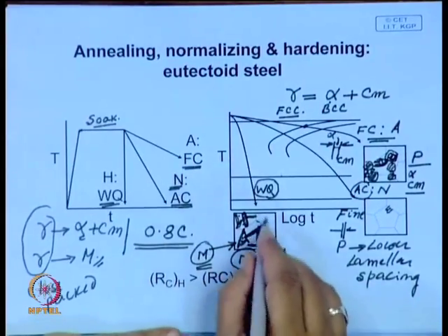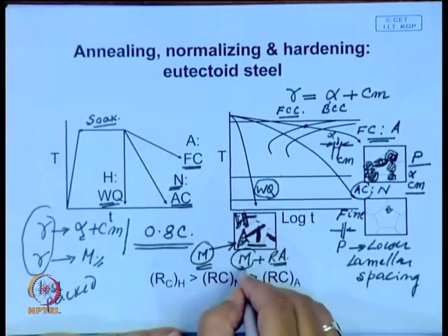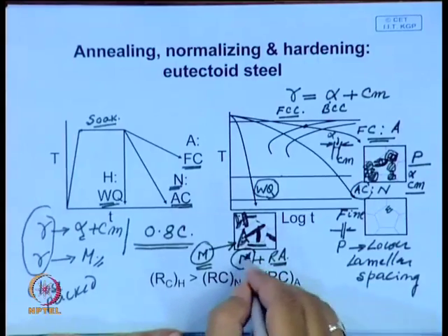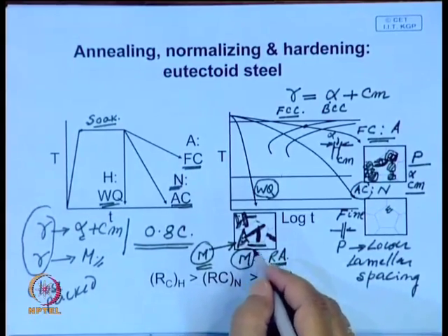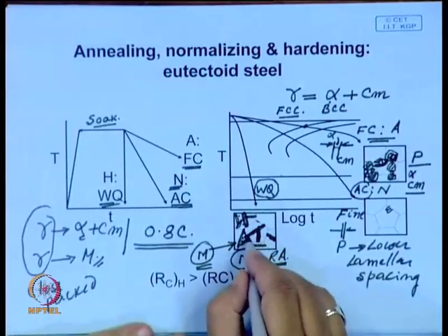The structure will be so fine that it may not be resolvable. In fact, under an optical microscope these martensites are very bright, and they often do not etch well, although the boundaries do.